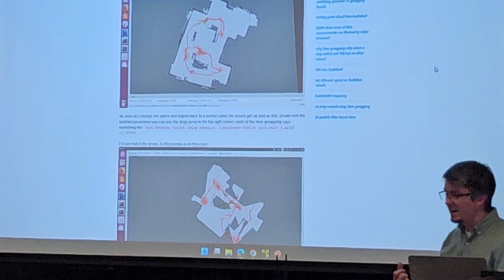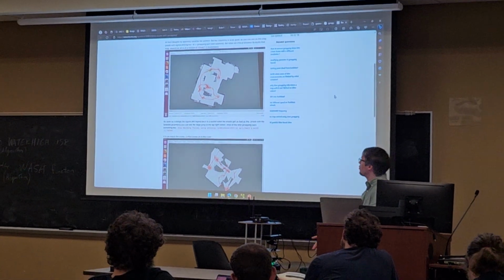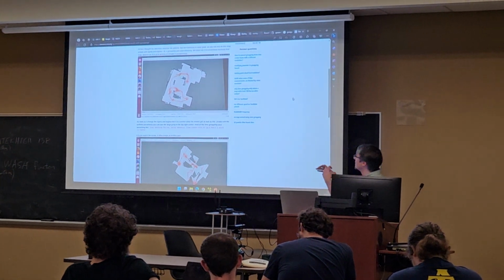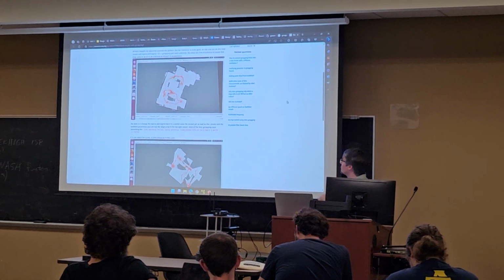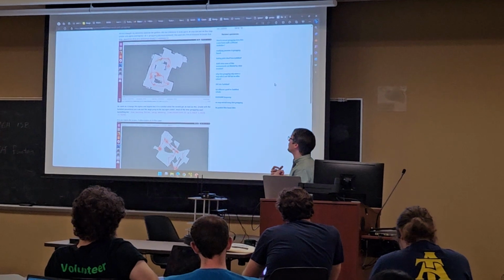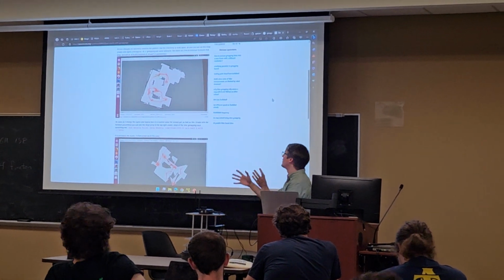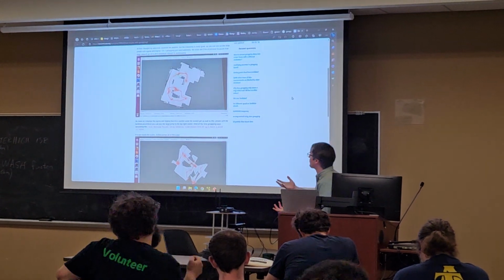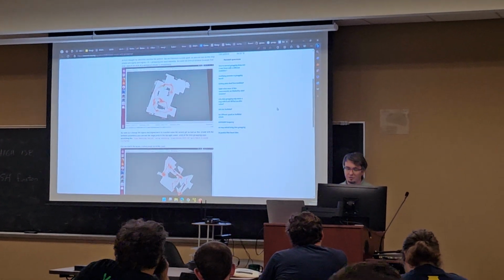So anything that's easy for the robot to recognize over and over as it moves around in this environment. And so it'll track these landmarks, it'll track its position relative to those landmarks, and then it will take its laser data and populate this map that we see here. So we can tell what spaces are free for us to move through and what spaces are not.